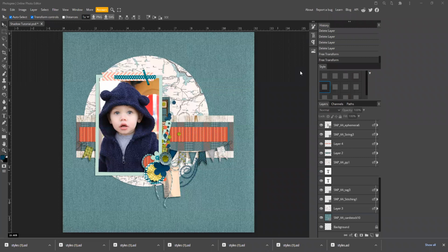Okay, for this tutorial, we're going to learn how to use the alignment tool and to also add a title and text to our layout. So first off, we're going to talk about the alignment tool. And if you have your move tool selected up here in this toolbar, you'll see these little boxes. And that's what you use to align things.